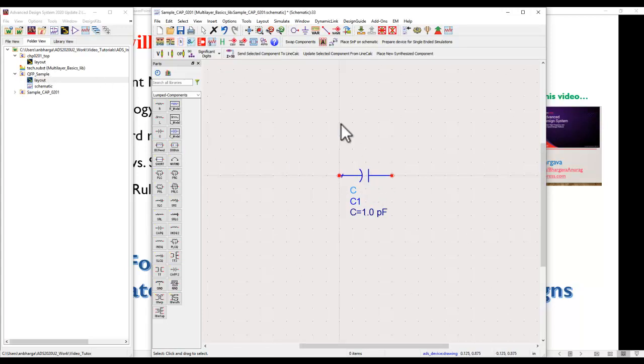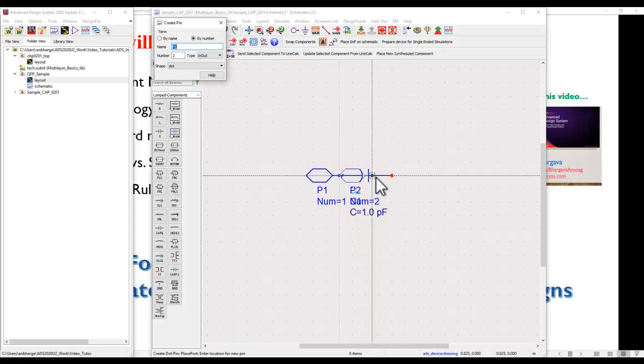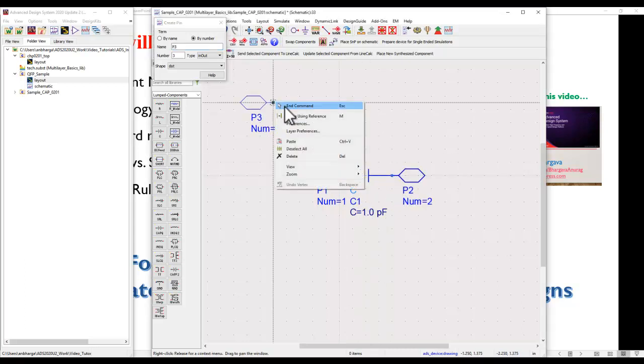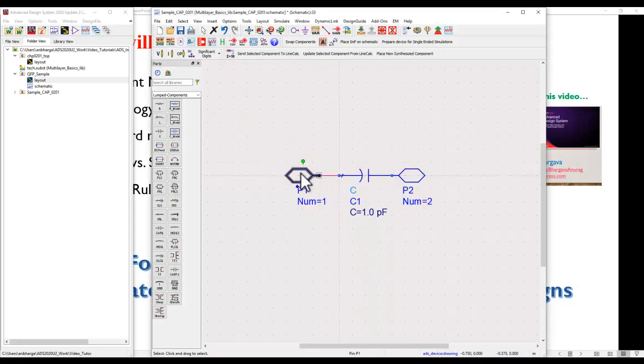So let's see all the steps. First, because this model will be used as a sub-circuit, we connect 2 pins. And remember, these 2 pins have a significant meaning. The one pin will be at the origin. So whenever you place this component in any schematic, you will always have your contact point here, and this is the origin point, right? This is how the symbol will rotate or move or shift whenever you try to drag and move it. All right, so we have the component.